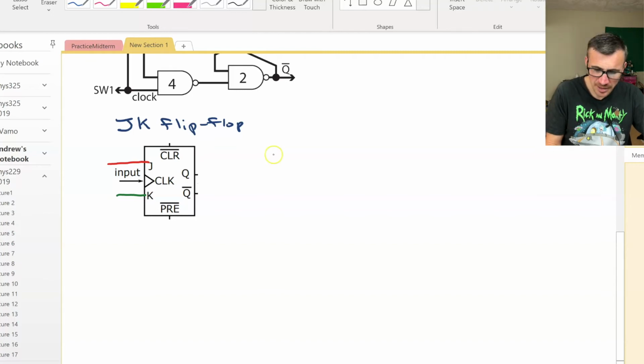And basically what that means is it has a normal clock input, but it's capacitively coupled. We remember this from our RC circuits and also from our high-pass filters analysis. If I have an RC high-pass filter like this, it's going to get a big spike when you get the sudden change, and then it'll do this exponential decay like we're used to, and it'll spike the other way.